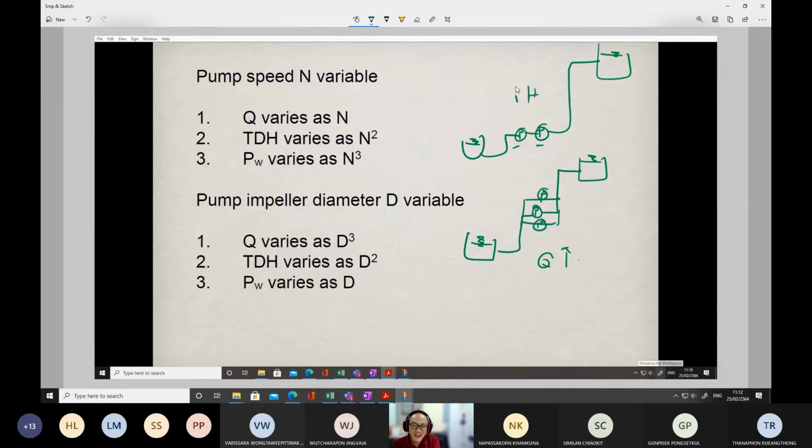So you will achieve a higher head once you connect two pumps in series. But for the flow rates, if you need higher flow rates but other things remain the same, you may connect one or two more pumps in parallel like this. Okay, so this is how we arrange the pumping system in both water treatment plants and some other places.